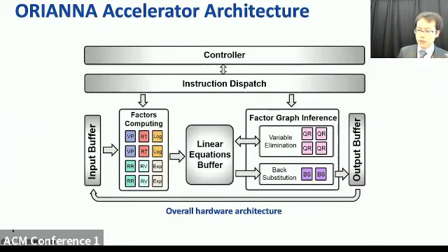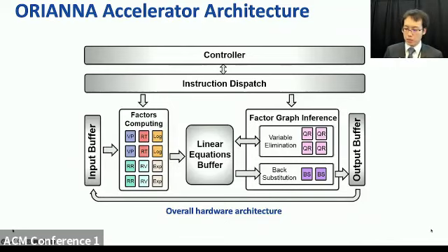And this is the overall architecture of our generated accelerators. The vector computing module on the left is responsible for the forward traversal and back propagation to construct the linear equation systems. And the vector graph inference on the right is to solve the linear equations, and also the instructions can be executed in an out-of-order way in this accelerator.